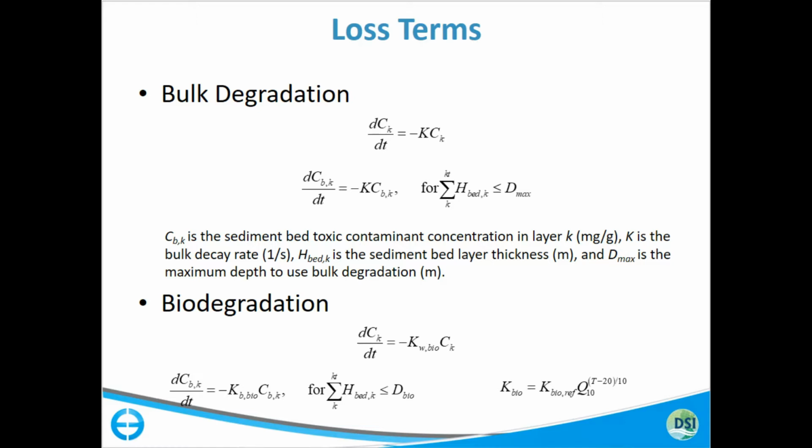Now biodegradation, pretty much the same set of equations, other than the fact that now K is a temperature sensitive coefficient. And we're following this Q10, this is following the WASP 7 and 8 approach for calculating temperature dependency of your biodegradation rate.